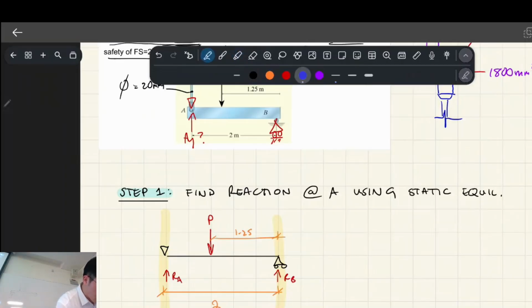Basically, when we're doing our moment equation, which is very basic, we have force times lever arm. And we have 2 unknowns: the reaction at A and the reaction at B. There's a cheat that we can do in order to make it so that there's only one unknown in the equation, and that's setting the lever arm of one of them to 0.